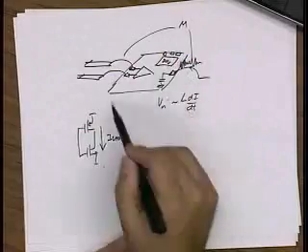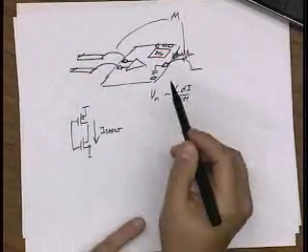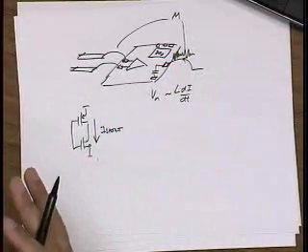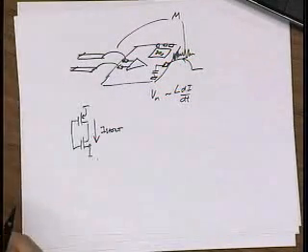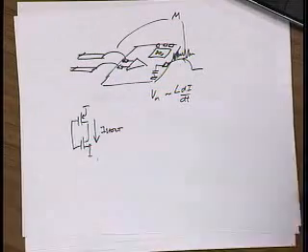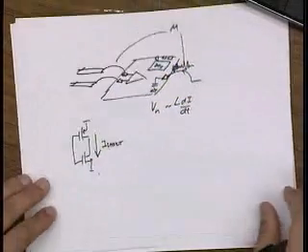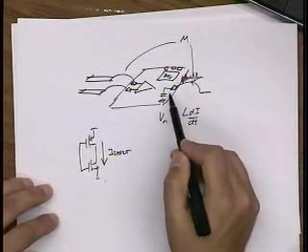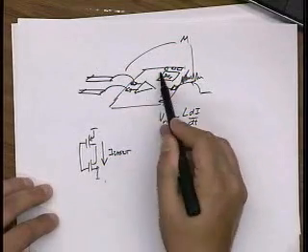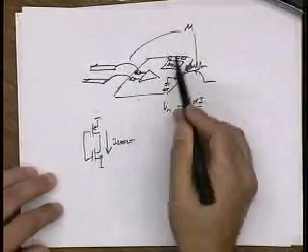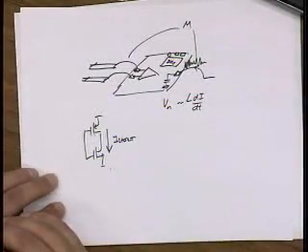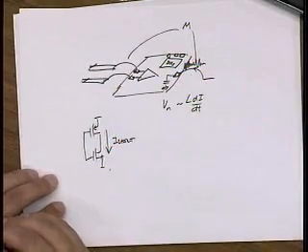So when you design your package, you don't do it blindly. You actually look at the most sensitive nodes in the circuit and try to make sure that they have a symmetric relationship with noise sources. Okay? So for instance, if you can't put your supply right here, you might have two supplies, and you might be able to put one here, and hope that they have roughly the same signal, and so you pick up common mode. Okay? Questions or comments?